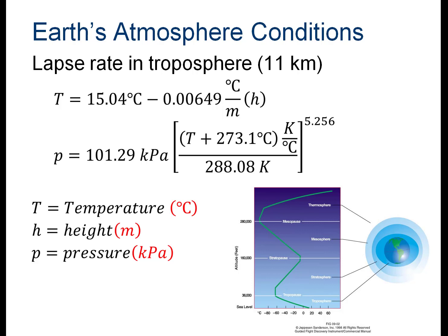Now the pressure goes down, not quite linear. Remember I said it's kind of linear? It's actually to the 5.256 power. You're like, huh? Yeah, that's what the model is. And this just says that I start out at 101.29 kilopascals, standard day at sea level.